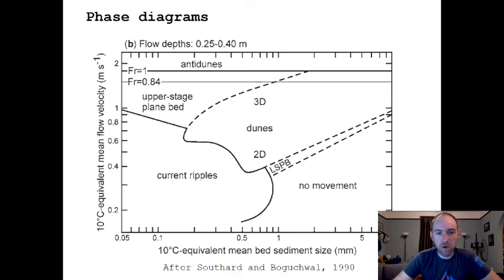And I think from other information that I saw that the flow depths were around 0.5 meter, or say it's 0.4 meters since we're on that slice here. Okay, well, I think we're probably in a flow velocity of somewhere between 0.4 and 0.7 meters per second, right? So it allows you to make that first-pass estimate of where in the flow velocity space your flow might have existed. So you can imagine where that might be useful.